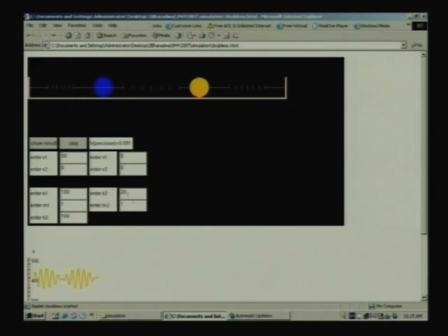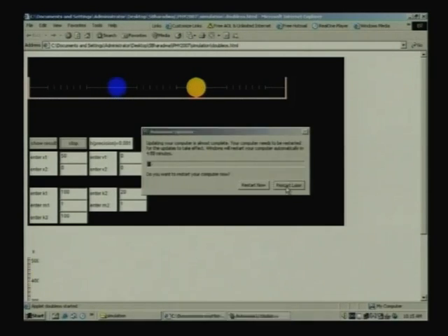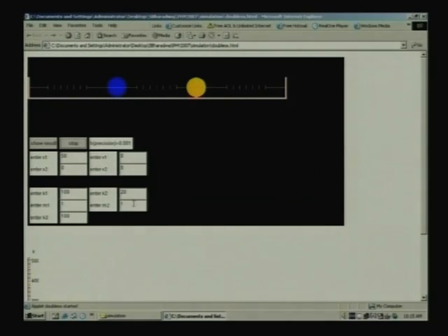Now, we could see what happens if I increase the coupling between the two oscillators. If I increase the coupling, I would have to increase the spring constant of the spring in the middle. So, I am increasing it to 50, and I would expect the modulation to occur faster. I would expect the oscillations to go from here to here and come back much faster. So, let us see if it happens. This is what our analysis leads us to believe.